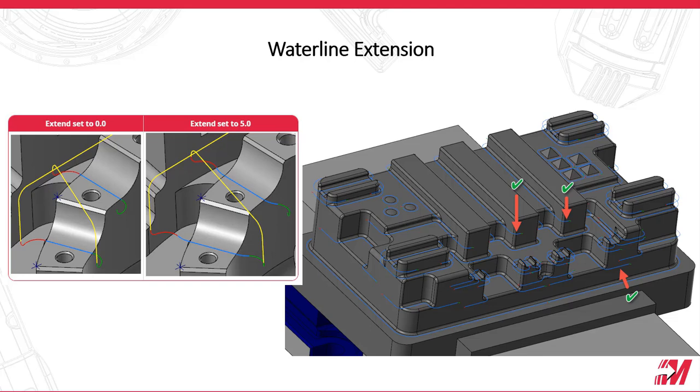This is really cool on the picture to the right. If you look at that, what that'll do is you can extend those cuts. And even though the floor ended, you can extend it, let's say, an inch, and it follows the profile of that solid out. So you're not going to gouge if you extend anything. It's model aware, so it just keeps on extending around that geometry, as you can see in the pictures, which is really nice for blending. You know, as you can see in this part.